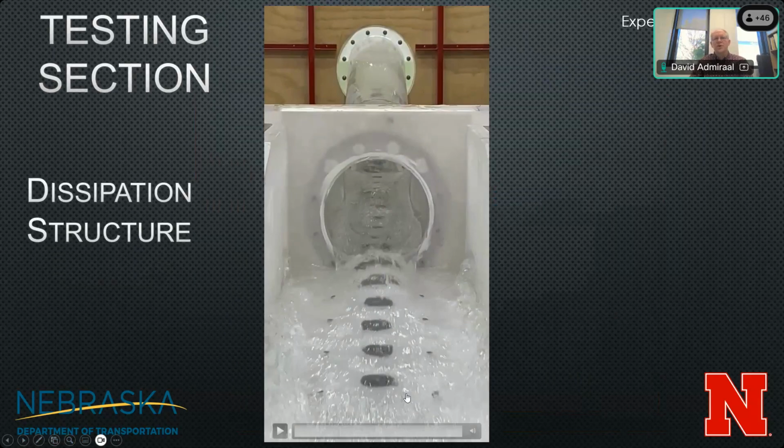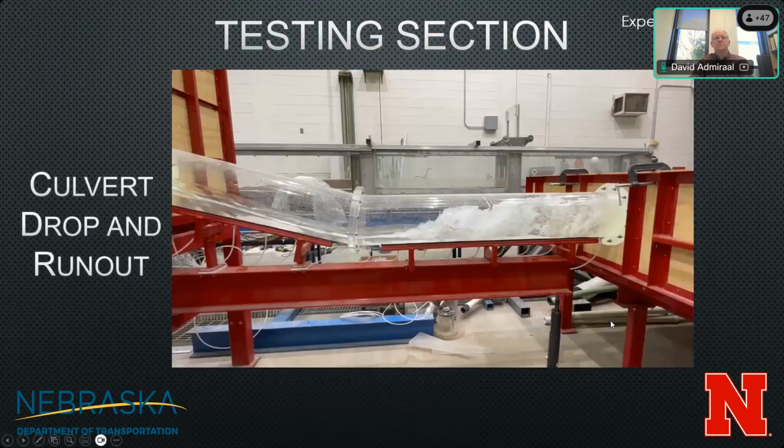They don't stick out in the flow at all, but because the water's so clear, you can see them real easily. So this is all flat and flush, and you can see that those little piezometers go all the way upstream. So we can measure depth anywhere. As it turns out, the velocities are so high and so turbulent that they don't work all that great. So they worked, but not perfectly for the flows that we did. And so we had other methods of measuring depth as well.